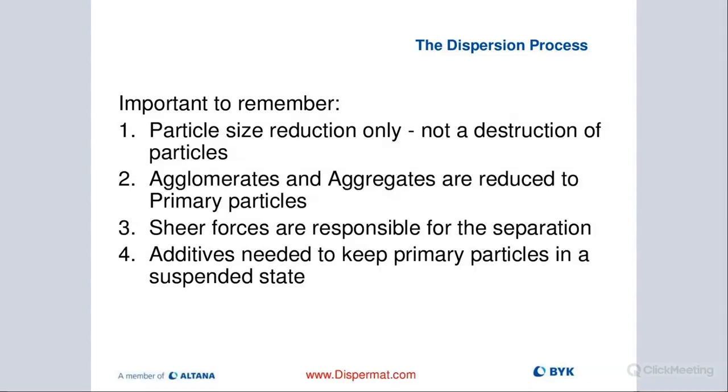And that pushing motion is actually the shear force that's created by the beads. And that's what's causing the breakup of the binding forces. So it's very unlikely that two beads will actually catch a pigment particle right in the middle where it gets crushed. So most likely it just gets pushed out of the way.